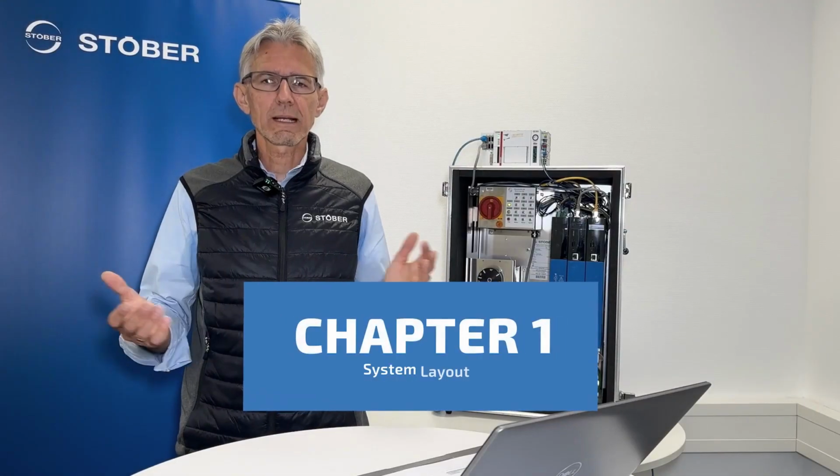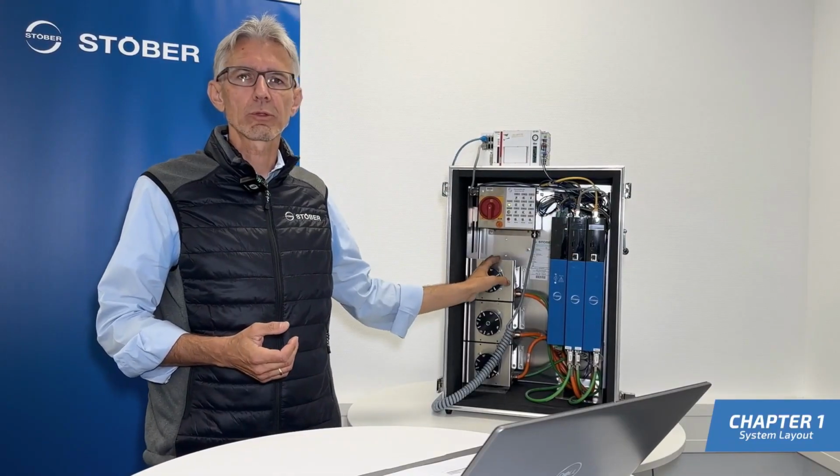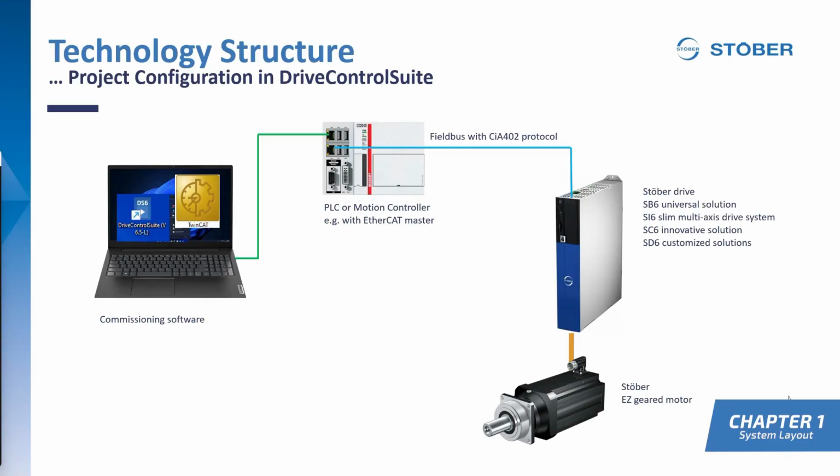Previously, I introduced you to the device profile CIA402, and now we can put that to good use right here. Once again, we'll need a controller and STOBER drive technology, and motors for the movement. For this, we need a controller with the TwinCAT runtime and the EtherCAT master, as well as drive controllers from STOBER Antriebstechnik 6th generation SB, SC, SI, SD, with a STOBER gear motor, synchronous servo motor EZ, and one cable technology OCS.